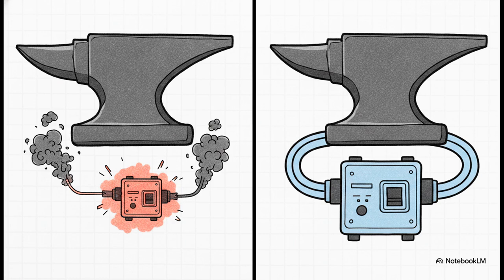It matters immensely because physics simply doesn't care about the useful part. It only cares about the total. Your cables, your transformers, and your upstream protective devices must be physically sized to carry that full 100 kVA of apparent power. If you mistakenly sized your infrastructure based only on those 80 kilowatts of useful active power, your equipment would be dangerously undersized and at serious risk of overheating or catastrophic failure.